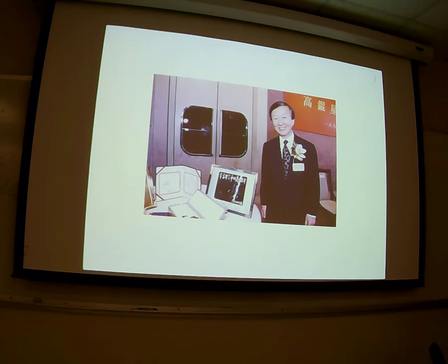When you talk about copper, coax, for the frequencies we're talking about, we get maybe 200-300 dB, which means the signal's dead. Now, the reason that's important: if you can transmit a signal with 20 dB of loss over a kilometer, then about a kilometer away, you get something that catches that signal, amplifies it, and resends it. You keep doing that, and it means the signal can be sent an enormous distance with a few repeaters every kilometer, and that saves a lot of money. So that's important. Let me keep going on.